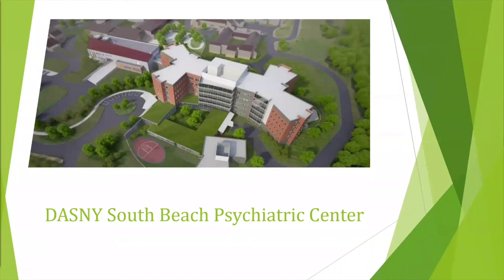This is another healthcare facility that's in construction in the Bronx. This is an interesting site because it is right next to the water on the boardwalk in Staten Island, and was devastated by Sandy as well. So they really wanted to look at options that were natural to prevent the facility and the site from future storm issues. So what we did is we really recreated the grading throughout the site so that we could actually create these natural berms and natural infiltration basins. So there's actually 6 of them around the site.